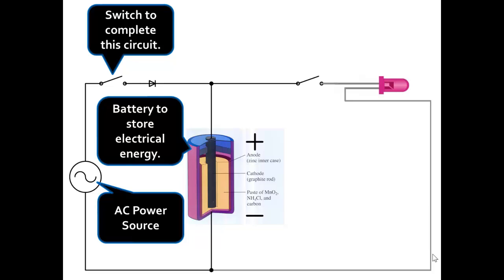That's actually a diode or a rectifier, because we have an AC source, meaning the current is going back and forth. It's switching direction 120 times a second, which gives you 60 hertz, 60 cycles. A complete cycle is current goes one way, then goes the other. That's one cycle. So you get 60 of those a second. But we only want current to flow one way through that battery, and that's to charge it. That's why we have that diode in there.